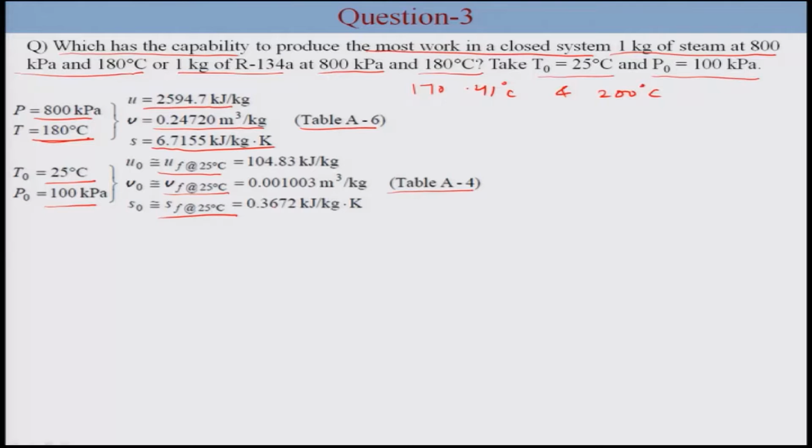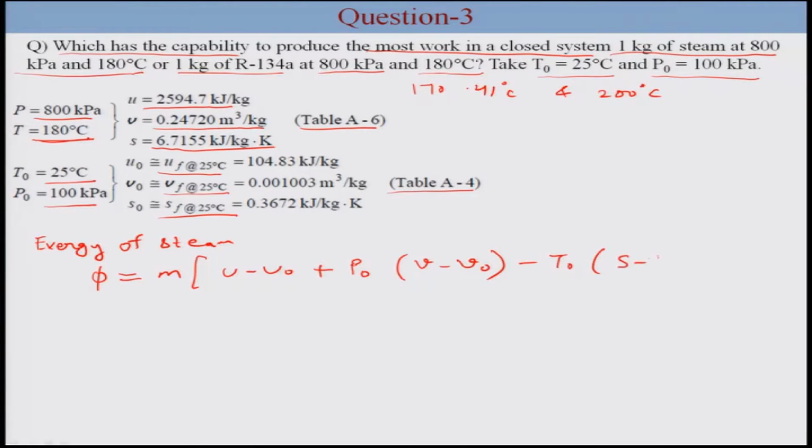saturated liquid. Now, the exergy of this steam is a measure of the work potential. So, if we calculate exergy of steam, this is equal to m(U minus U0) plus P0, which is the pressure of the surroundings, into (V minus V0) minus T0(S minus S0).